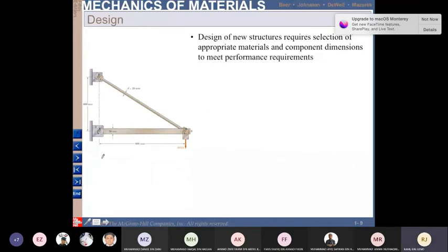This is your stress equal to F over A. So stress is 100 MPa and F is equal to 50 kilonewton over pi d square over 4. So you change this 100 MPa to times 10 to the power of 6 and 50 to times 10 to the power of 3. And then pi d square over 4.